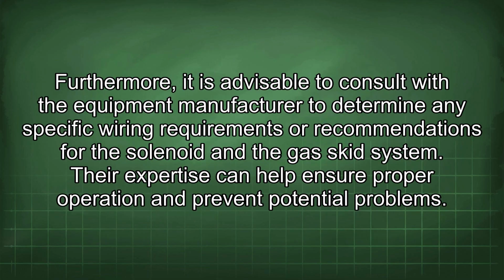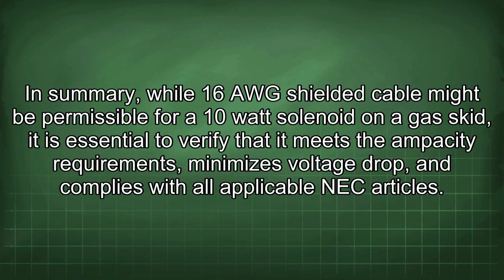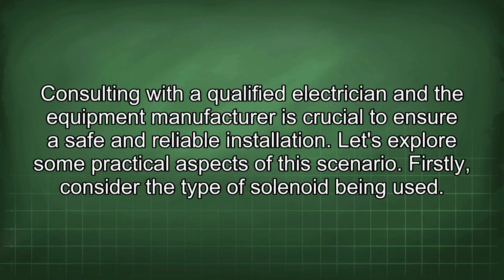devices. Furthermore, it is advisable to consult with the equipment manufacturer to determine any specific wiring requirements or recommendations for the solenoid and the gasket system. Their expertise can help ensure proper operation and prevent potential problems. In summary, while 16 AWG shielded cable might be permissible for a 10-watt solenoid on a gasket, it is essential to verify that it meets the ampacity requirements, minimizes voltage drop, and complies with all applicable NEC articles. Consulting with a qualified electrician and the equipment manufacturer is crucial to ensure a safe and reliable installation.